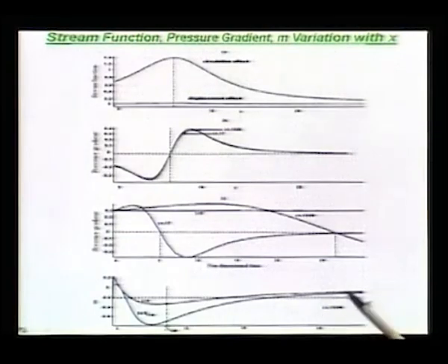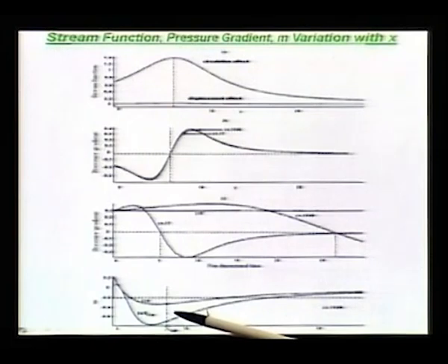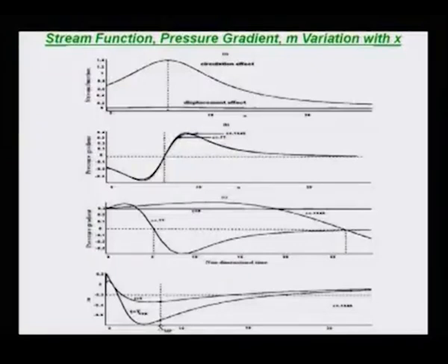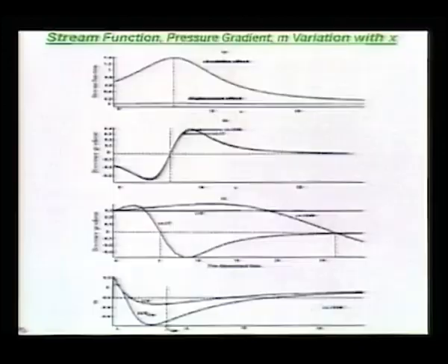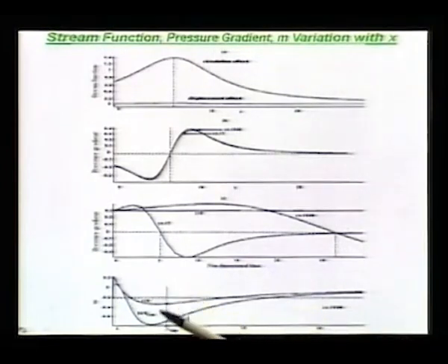So, even at the initial time instant, we have a range of x where you have adverse pressure gradient that is more adverse than what you get for steady separation. So, in a dynamical sense, you do create a much larger adverse pressure gradient. And if you keep looking at this snapshot as a function of x, shown here for t equal to 0, at a later time you can see it keeps becoming more adverse, over a longer stretch, and even the adversity increases in quantum.